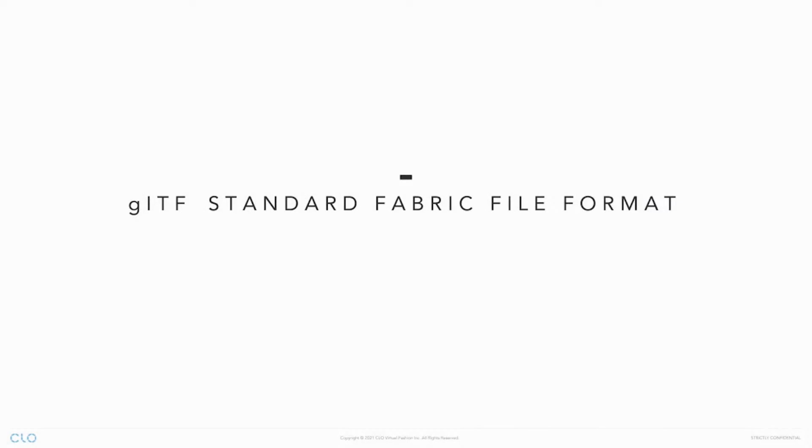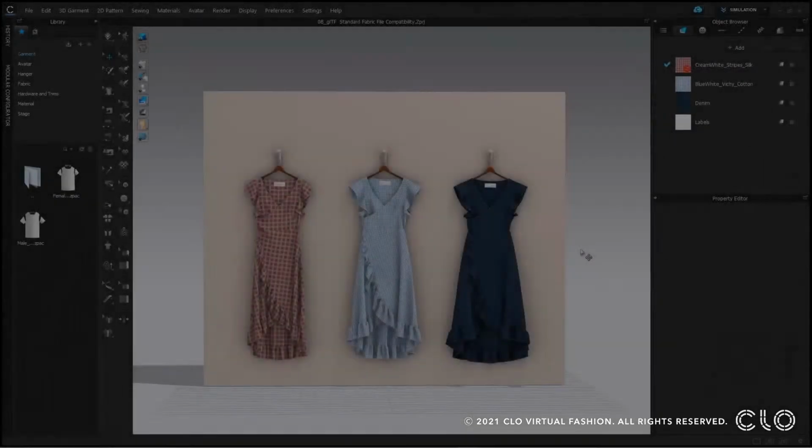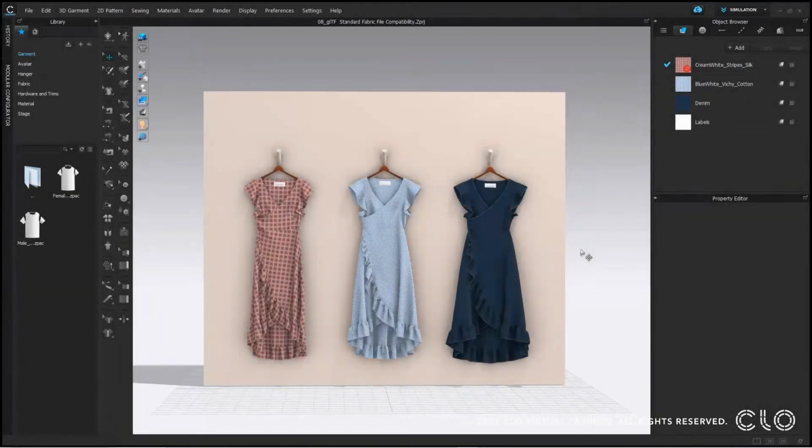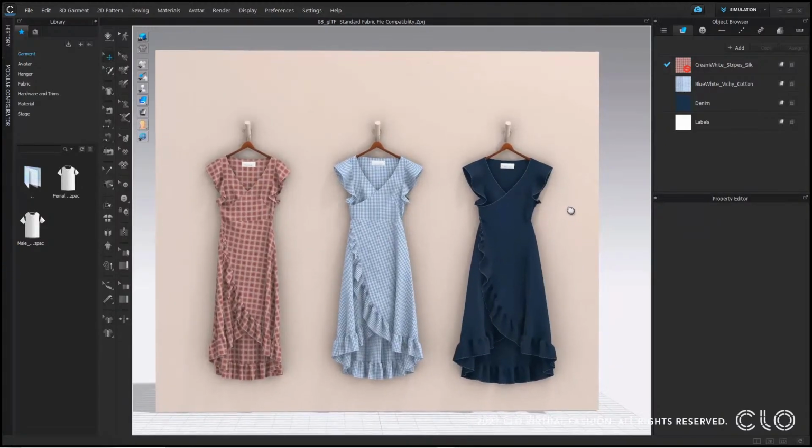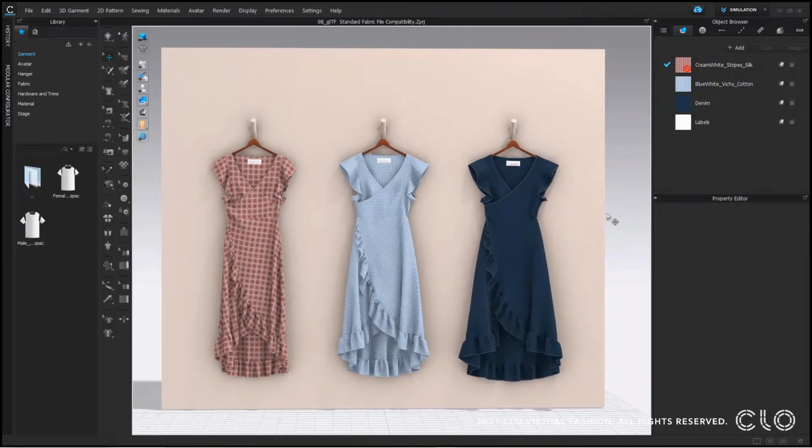We decided to use the glTF format to export both visual and physical parameters of a fabric, because it is a format that is already extended to share PBR materials amongst different 3D software. Furthermore, another benefit of using glTF or GLB format is it is flexible and extendable, and we can always add more information by writing into the extension sections.